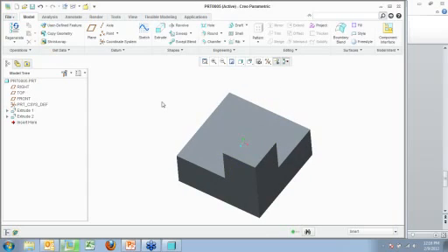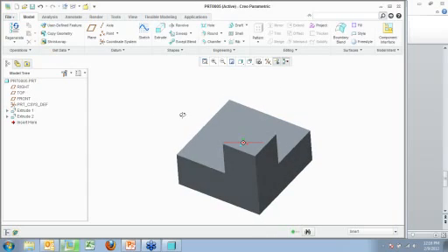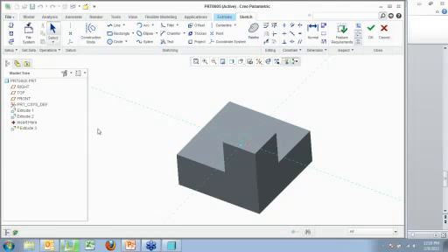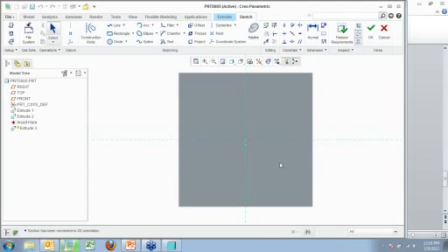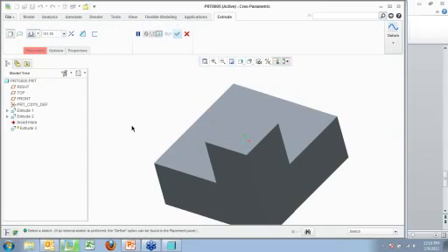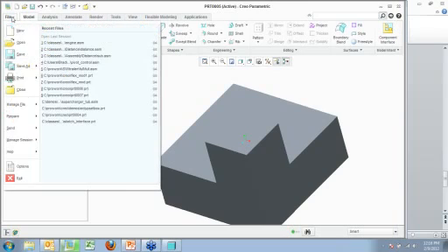I know some of you guys right now are probably getting a little agitated because you don't like that when I create an extrusion it doesn't reorient, because that's the way it's always been done, and that's the way I was used to doing it, and it took a little getting used to. You have a couple different options. You have a button right here, Sketch View, which will flip it to the sketch view, or if you prefer to do it like the old way, there's actually a Config Pro option, which I'll show you.